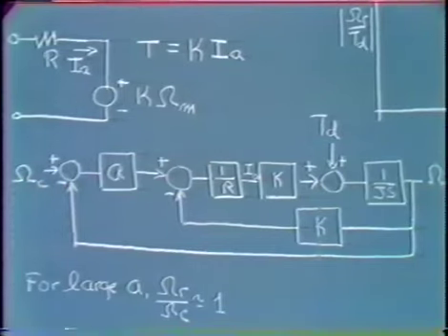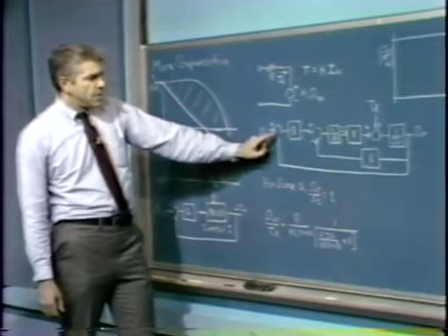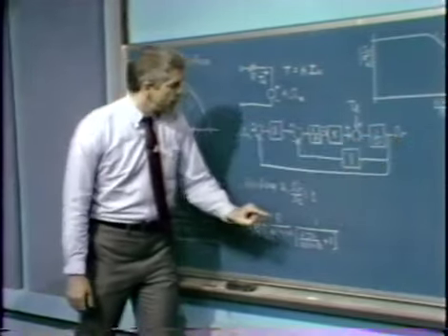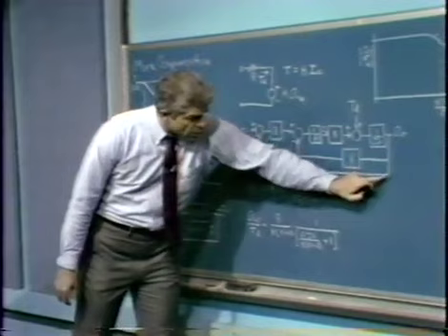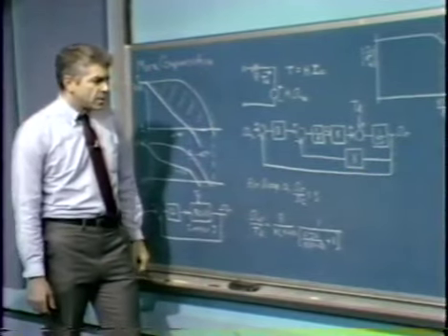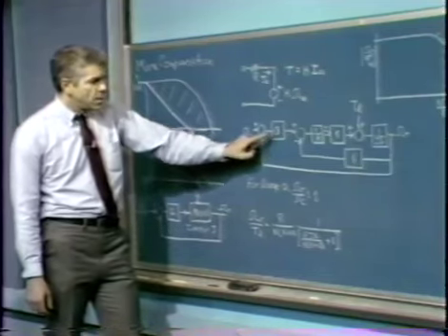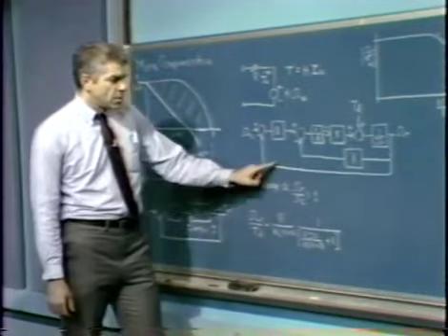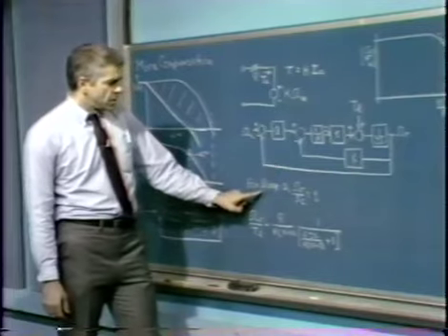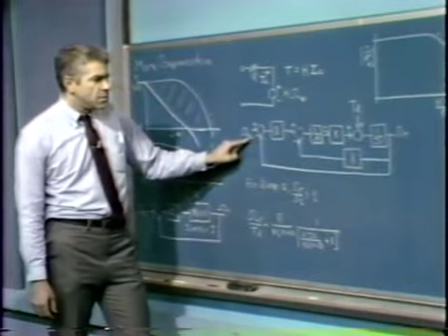Well, we can now look at the properties of this sort of a feedback system. If I have a sufficiently large value for A, we have a system that has unity feedback between the output variable and our input summing point. So we have a system which has a so-called major loop that has an F, or a feedback transfer function, of 1. And in fact, providing A is sufficiently large, the gain from the input of the system to the output of the system is about equal to unity, the reciprocal of the feedback path. And this tells us that for a large A, the response speed should be just about equal to the commanded speed.